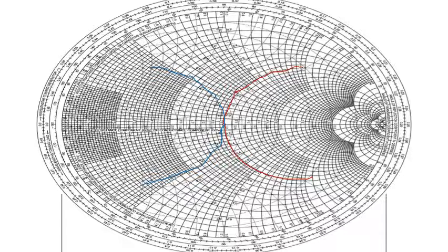So anything which is drawn over here, if you are passing through the solid circle, which is marked in red color, will always be drawn with a series connection. Whereas anything which is drawn on the dotted circle will always be drawn with a shunt connection. These are the first two rules for doing any lumped element matching. Suppose you are moving upwards. Now I'm using some other color, maybe yellow. Suppose I'm trying to draw a lumped element matching, and how do I start? Suppose I'm trying to go up.